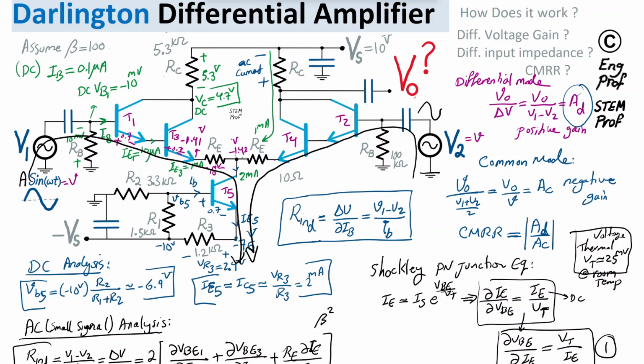So I don't need to analyze both branches, because from the perspective of input V, I have the same sequence of the effective resistance of transistor T2, the effective resistance of transistor T4, the impact of RE, all of these, as we discussed, ported to the emitter side, and then finally we have 2 times the equivalent impedance observed from the collector of T5.